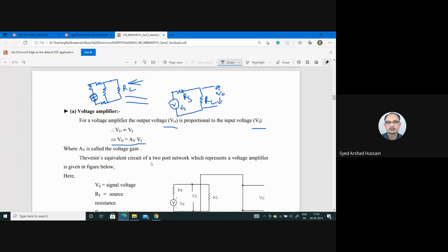from the output side, in the absence of RL, the equivalent resistance from here. Equivalent means here you can see, you can write this plus this parallel to this, say R1, R2, R3. That means here RTH is equal to, say, R1 plus R2 parallel R3. Okay, this is your Thevenin's resistance. So this is this. Okay, and this is the equivalent potential.